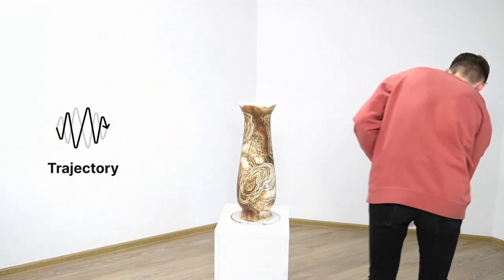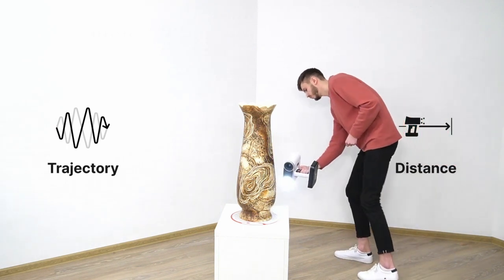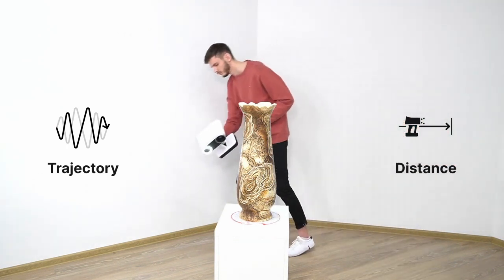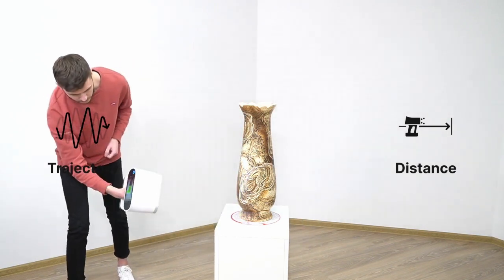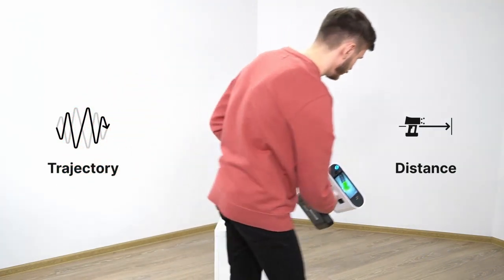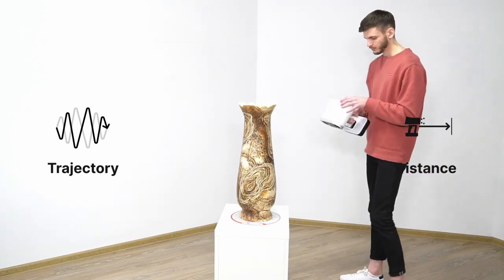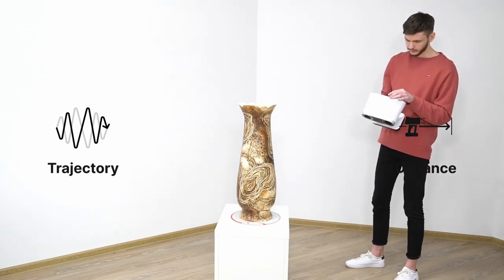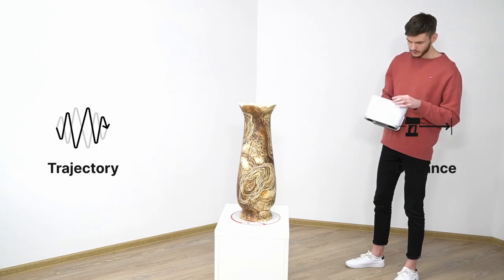Another important aspect is distance. This is something that you should definitely keep in mind. Both in Artec Studio and on the Leo screen, we can control distance through the use of the distance color map feature. The rule of thumb here is, by default, we want to be in the green zone, somewhere close to the middle of the depth of field. If we aim to capture the finest details, we should consider scanning closer to the nearest border of the field of view.